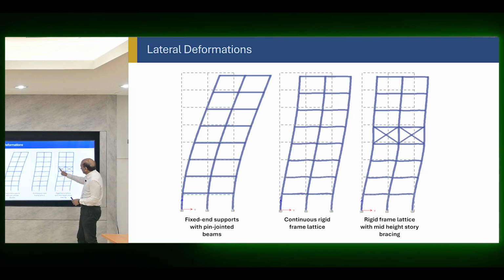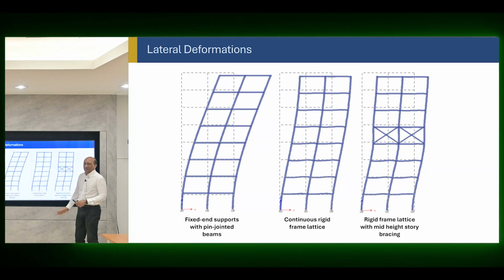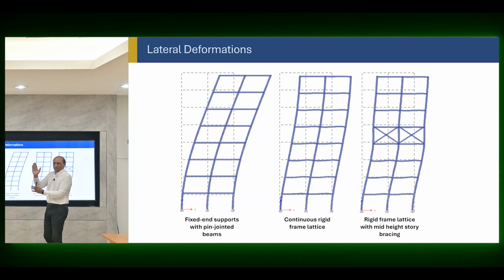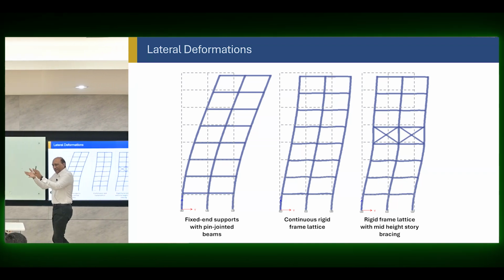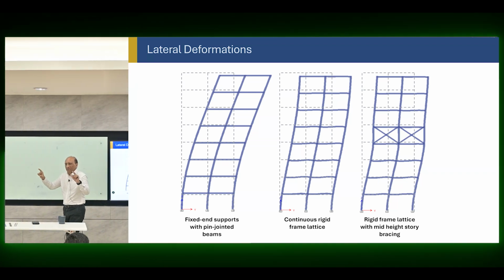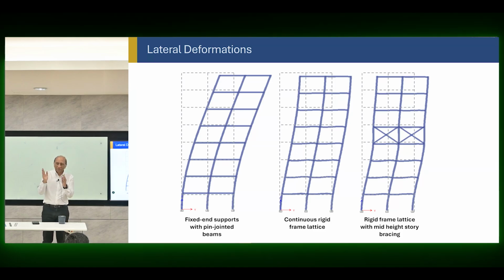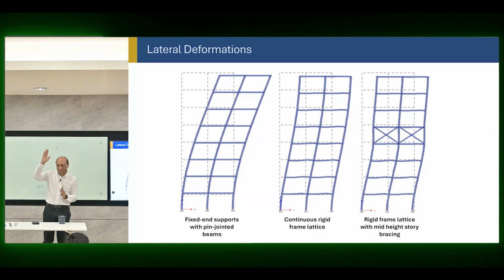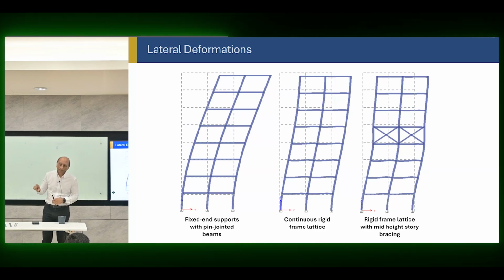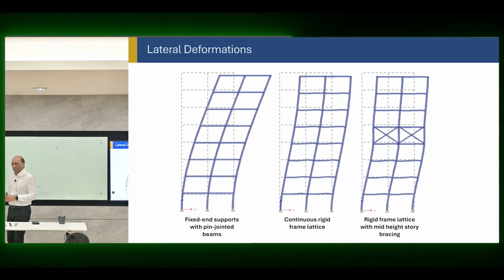And you can see here, if you just add some other system in just one floor, suddenly it affects the structure. You just block one floor and suddenly it has a stiffening effect up to that point, the structure becomes a little bit straighter, and then it alters the entire displacement above. Just one floor. If you make that floor braced or wall or whatever, we will see many things that can happen.